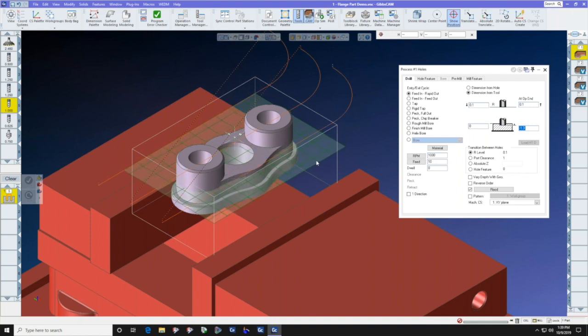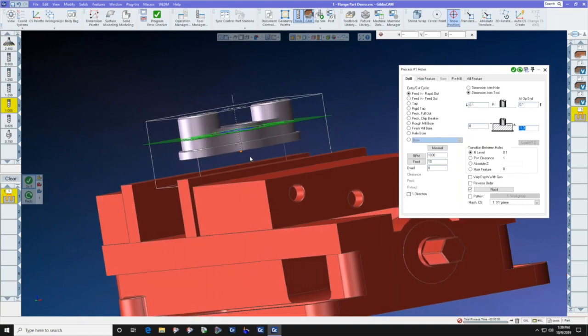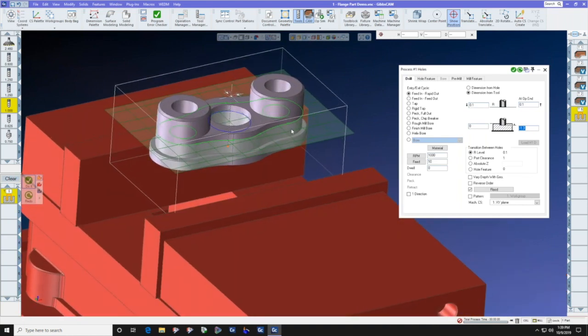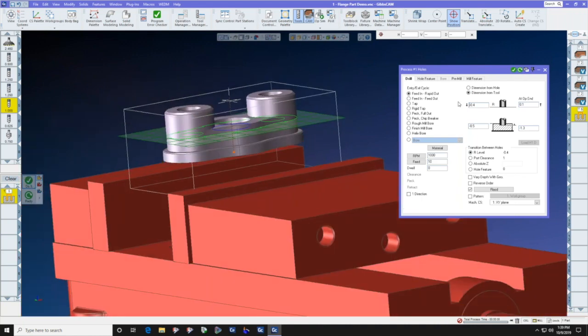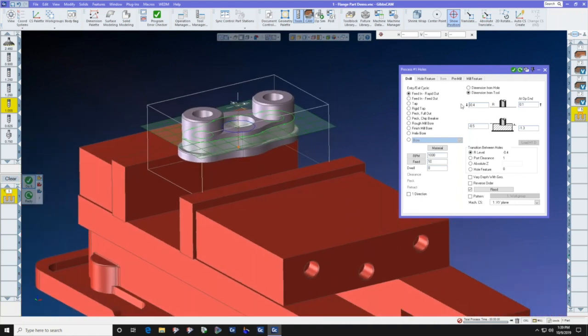Well, I simply want to drag it down into that hole, and yes, the profile of the hole is now lit up. I select it, it's blue, and look, the do it light is lit. If I click do it, there's my drilled hole. Now we do want to make a little bit of a change here. We want to start drilling at -0.5. So we will wrap it to -0.4 and redo. That'll be a more efficient use of our time when we're drilling this hole.